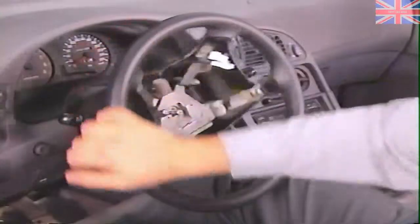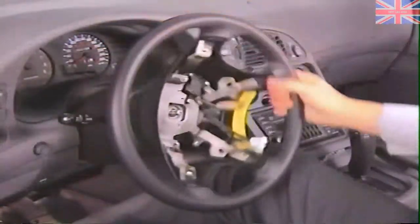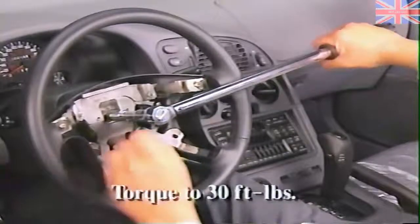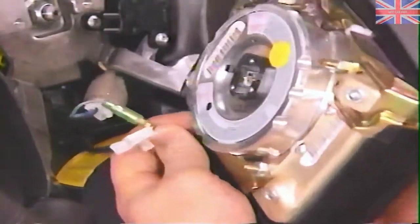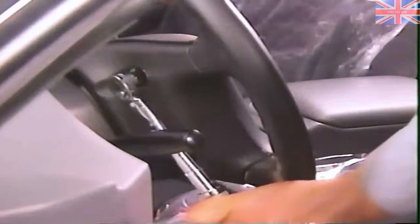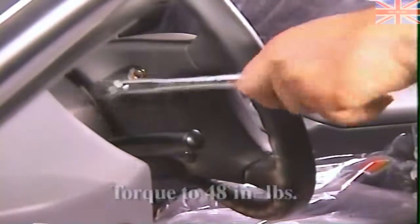Turn the steering wheel all the way in both directions to be sure it moves freely. Install the steering wheel retaining nut and tighten it to 30 foot-pounds. Reconnect the horn connector and the airbag module connector. And mount the airbag module on the steering wheel, taking care not to pinch the wiring. Install the 4 attaching bolts and tighten them to 48 inch-pounds.